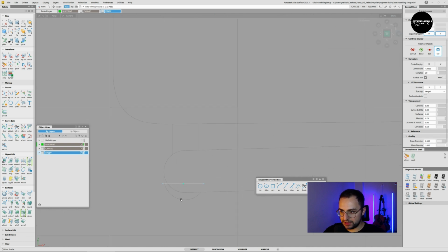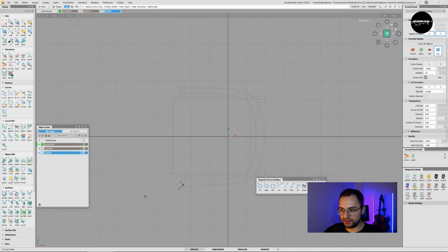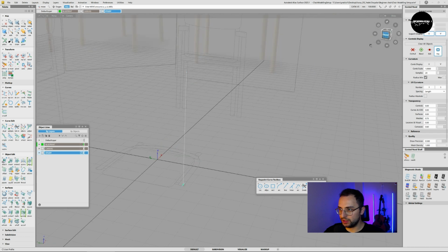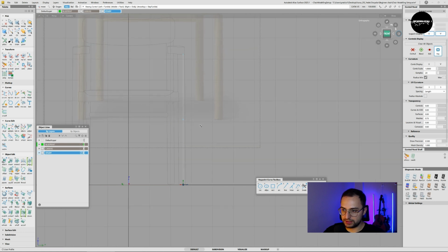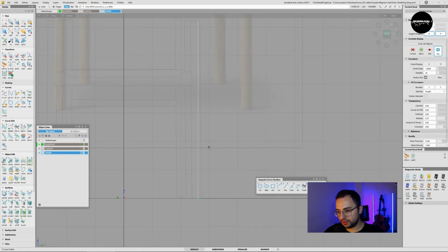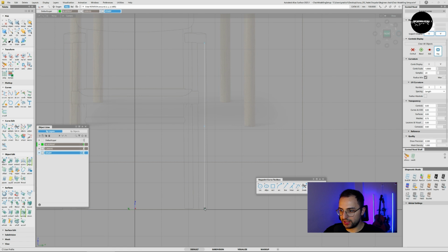I'm seeing something here and not, so that means this is more or less rotated from the front view. It could be. Let's go to front view, and you see this leans to the left a little bit. So let's use the rotate tool. Where is it? It's there. Since our pivot point is here, it's going to rotate from the bottom of the curve.